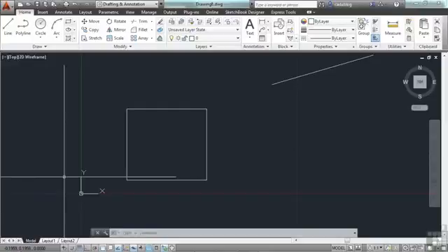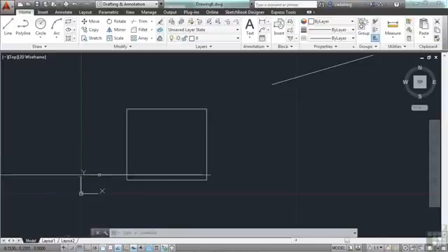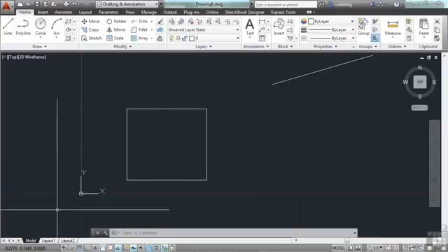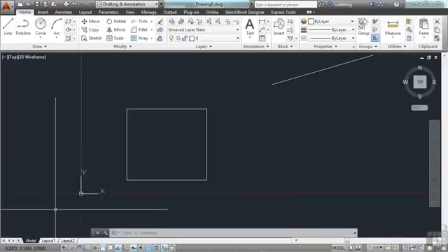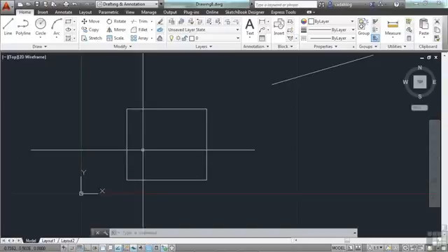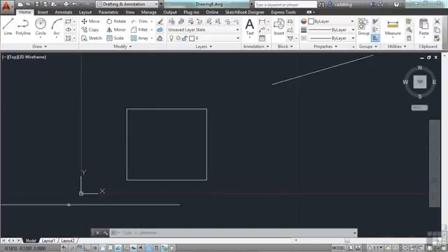So that also means that you can have negative coordinates in AutoCAD. And in math, the positive and negative values often indicate direction. So a positive direction in a line or in a coordinate means it's moving to the right or up. Negative is going left or down. It's the same sort of thing. When I move over here to the left and lower of the UCS icon, you can see my coordinates are negative. To the top right, they're positive. And the X and Y become positive and negative accordingly.